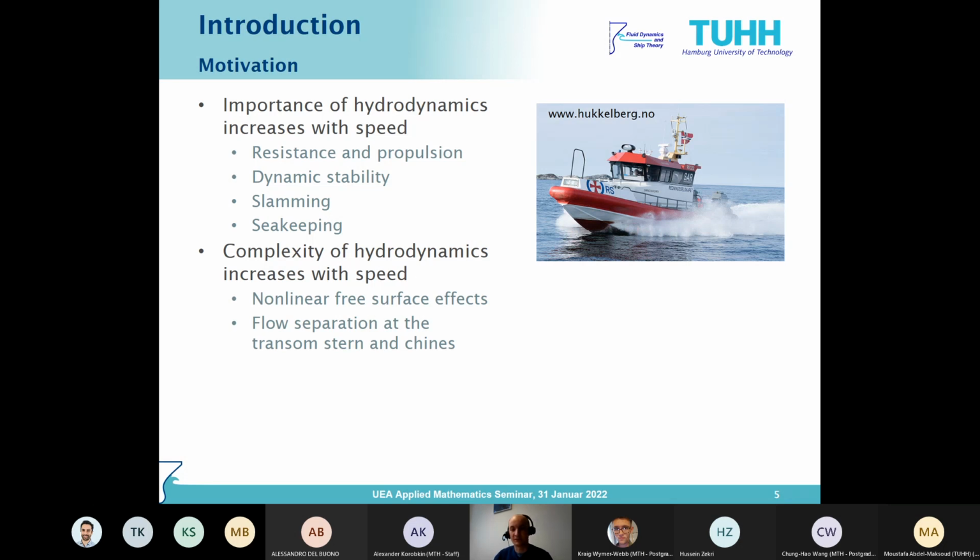For this reason, traditional potential-based methods, which linearize the free surface, usually don't yield good results or any results at all. Then there are more sophisticated methods like the finite volume method, which can capture free surface effects like this, but they cost a lot of computational resources. Especially for time-demanding simulations like seakeeping simulations, this may be a problem.